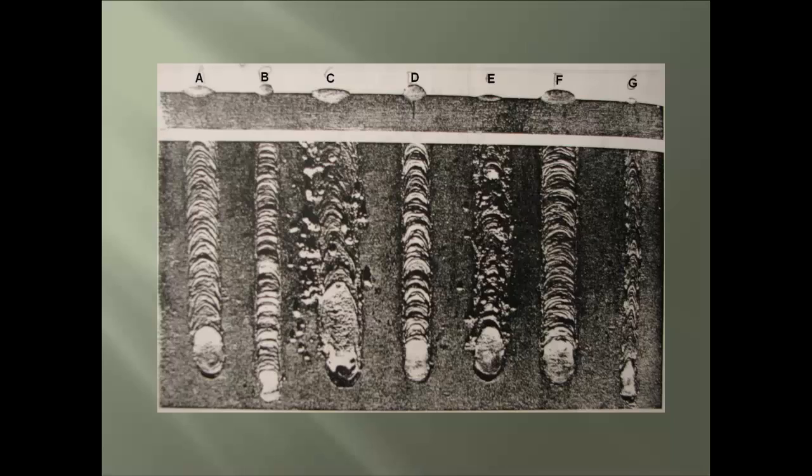And the last defects are the actual weld beads themselves that are affected by the weld current and techniques. So we see some major examples of weld beads. First, we see a proper weld bead which has the proper current and technique. Now we see a set of weld beads which show the slow. Now we see a set of weld beads which show the current being too low, then too high. Notice the difference between these two and the proper weld bead.